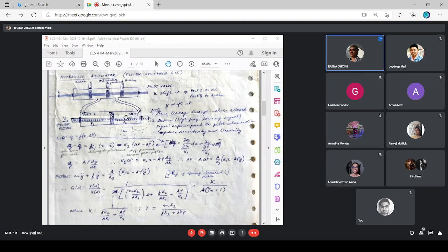But that is not the objective. The objective is to keep this in motion so that it responds easily whenever a definite input is given from the control system. So what to do then? Put a sinusoidal input here. A sinusoidal input is practically called a dither signal. What is that? A high frequency.